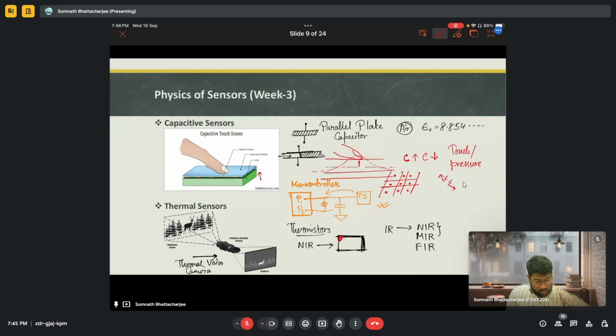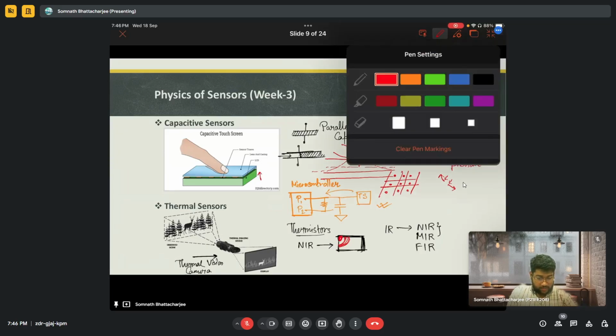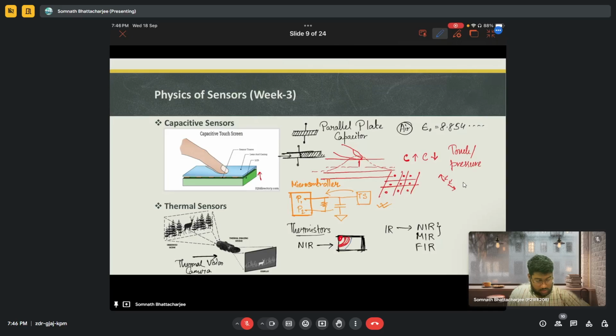Based on this area, we can get a direct image, and these are the cool places, right? Based on this, we can say there is an issue with this IC, and the issue is here because this is the center point, a higher thermal point.